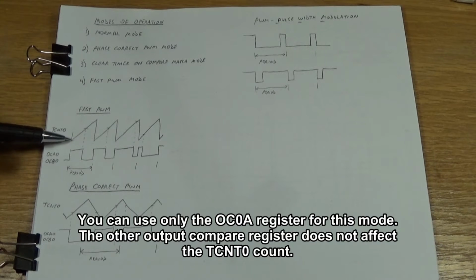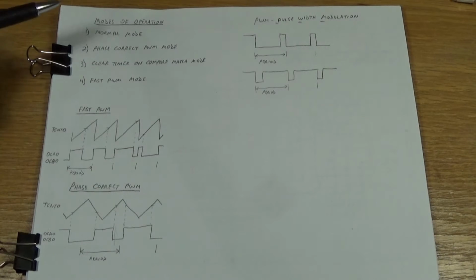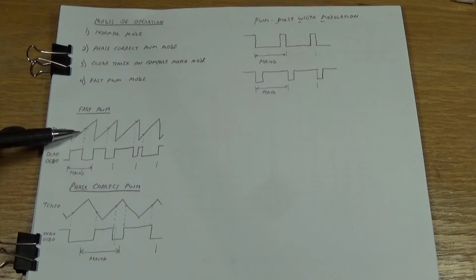That way you can set a fairly accurate time from 0 to where it matches, and then it generates an interrupt again. That's the method I showed you in the previous video, and that's how we got the 10 millisecond interrupt. And so let's look at the fast PWM mode first, which is this one here.